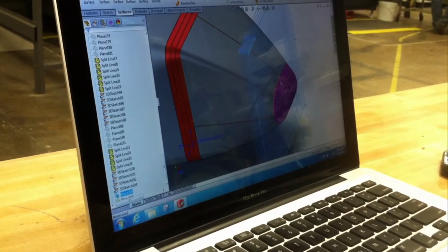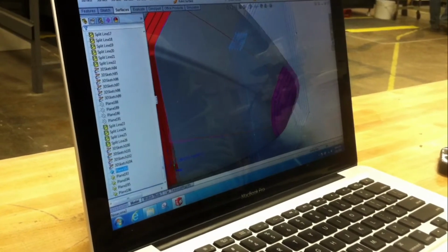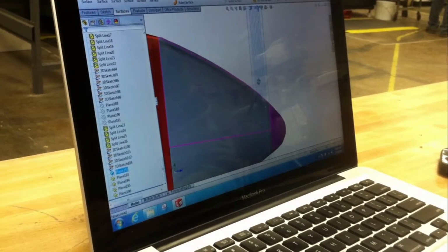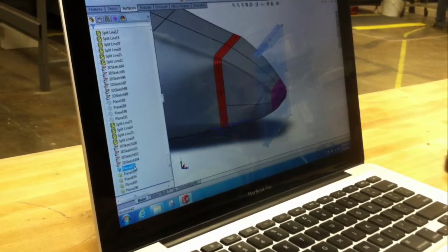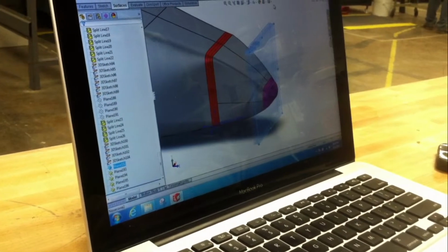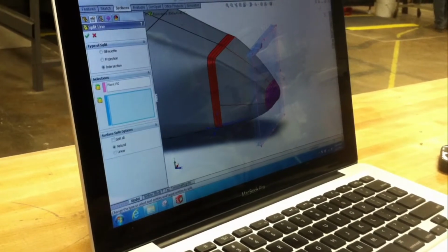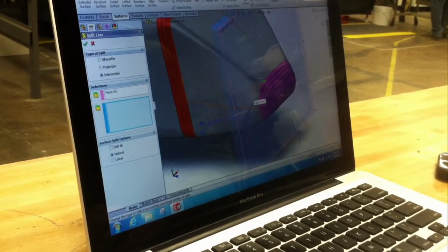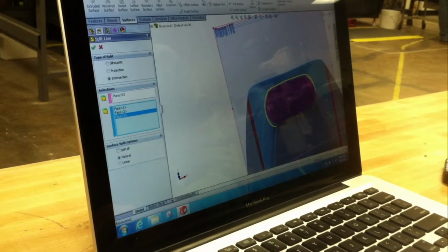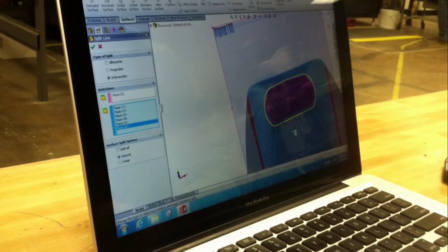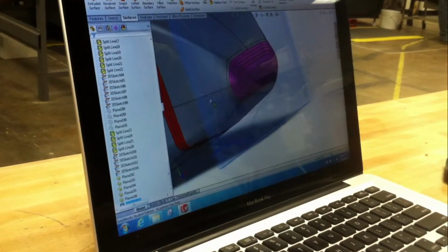So this first one should be, okay. So what you do now, I like to do this. I have all my planes here. They're all showing. I immediately go right to curves, split line. And since that plane's selected, I go to the surfaces where it's at. It'll show you the yellow line of where it's splitting it. Split that, hit the OK. So now that's split the line.